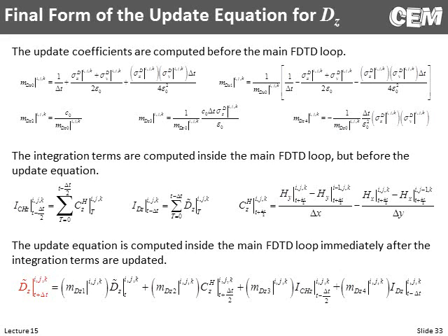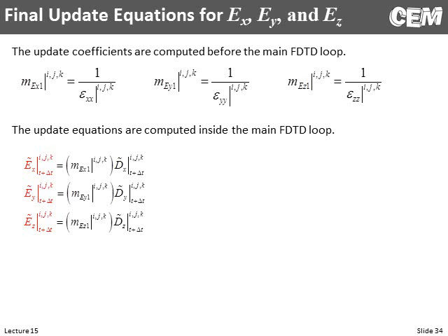And that one simple little constitutive relation we've pulled out, which is the next slide, we've pulled that out so that any kind of crazy dielectric response we want to build in, we don't have to touch the update equations for those previous field components. It's all here in a much simpler framework. But just for ordinary LHI materials, we have 3 update coefficients that are just the reciprocals of the dielectric constants, and we update our electric fields from the D fields with these reciprocals of the dielectric constants. So a really, really easy step.